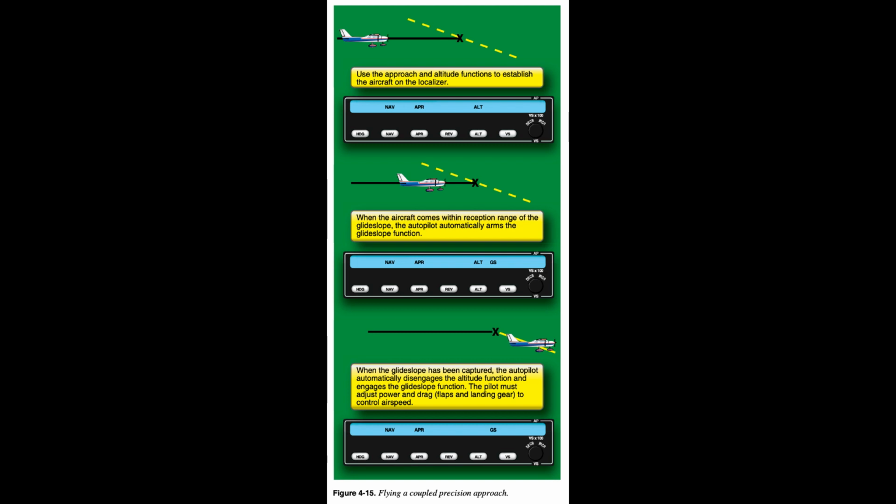Essential skills. 1. Use the FD/autopilot to couple to a precision approach. 2. Use the FD/autopilot to couple to a non-precision approach. 3. Use the FD/autopilot to couple to an RNAV approach. 4. Determine the power setting required to fly the approaches. 5. Determine the power settings necessary for level-off during non-precision approaches and go around power settings for both precision and non-precision approaches.